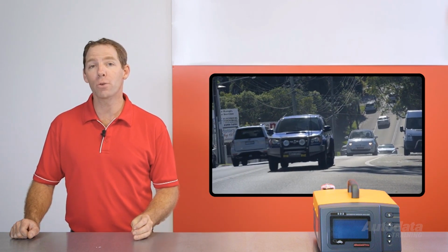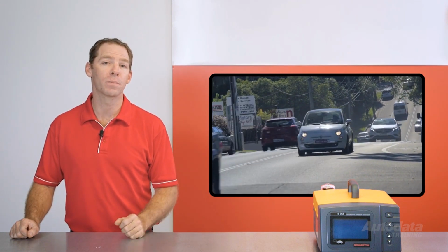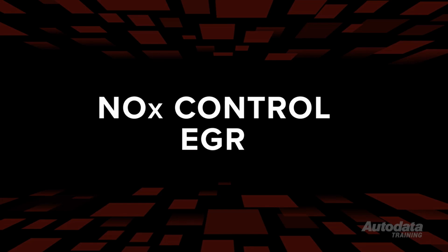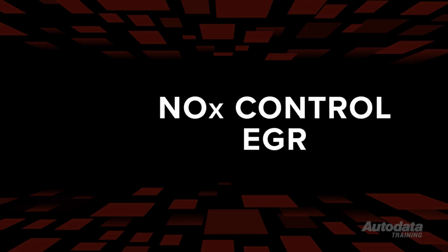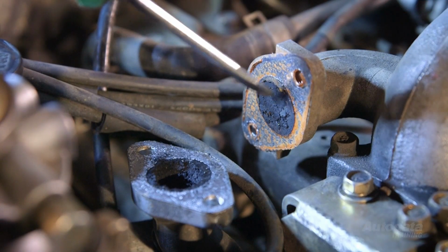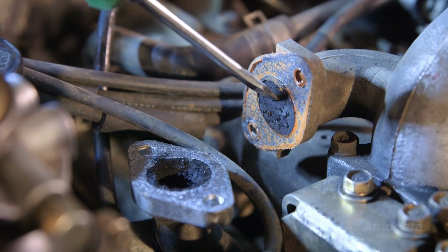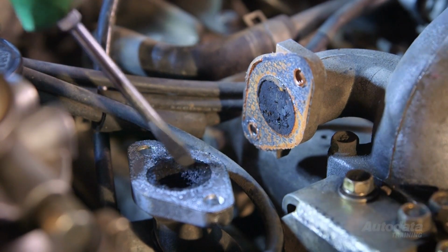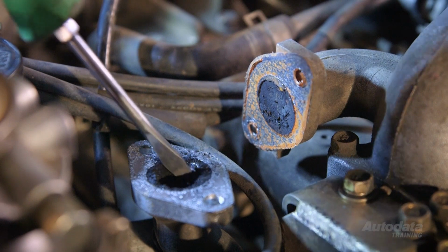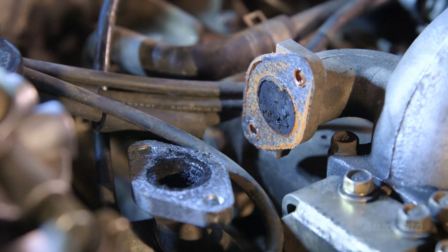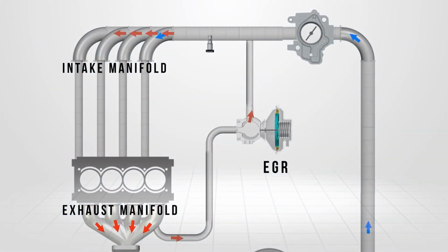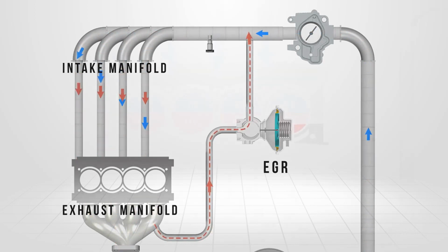Manufacturers have chosen several ways to control NOx emissions. Exhaust gas recirculation is the oldest and most common way to control this tailpipe emission. Unfortunately, it's also the most problematic. Very simply, a small portion of spent gas is taken from the exhaust manifold and channeled to the intake manifold, where it is drawn into the combustion chamber.